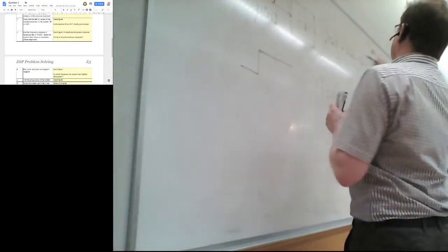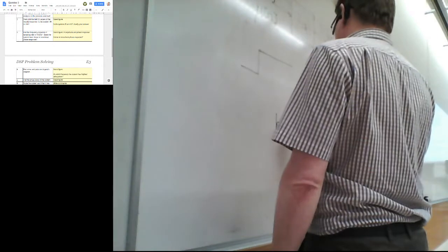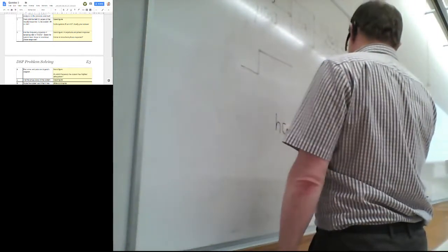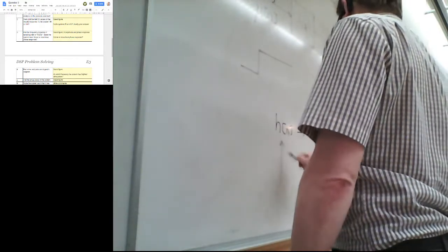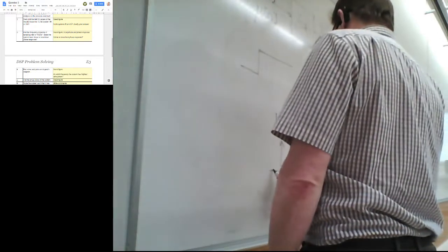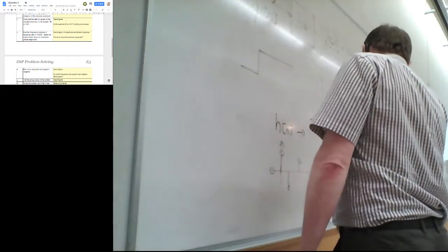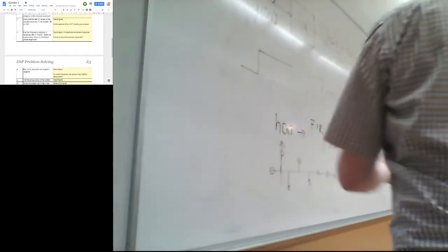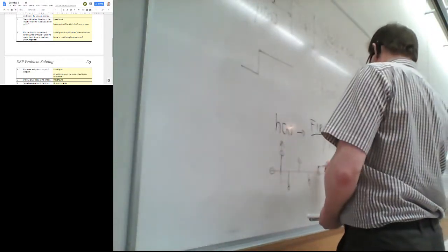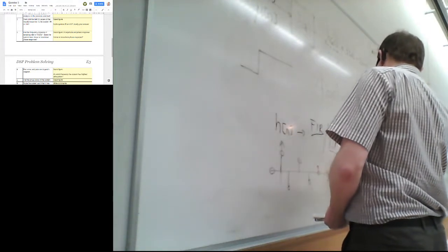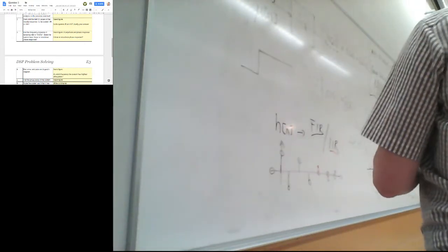How about this impulse response? Impulse response basically will tell you if the system is FIR or IIR. The only thing you need to do is to observe the impulse response, and does it end or not. So if it ends, that's FIR. If it does not end, then it's IIR. And how fast should it end?